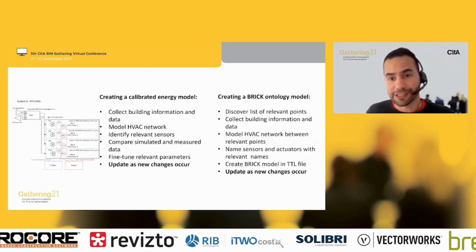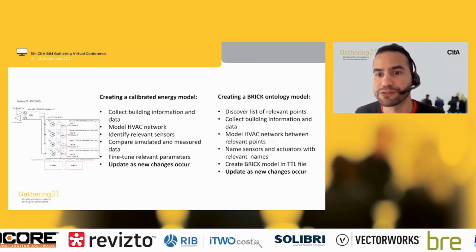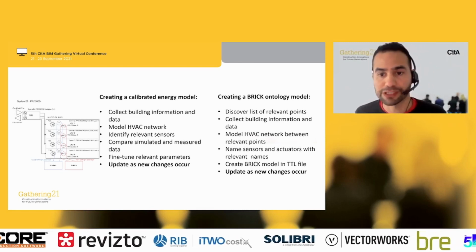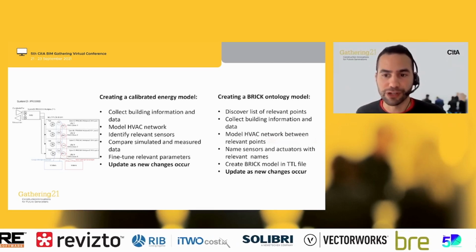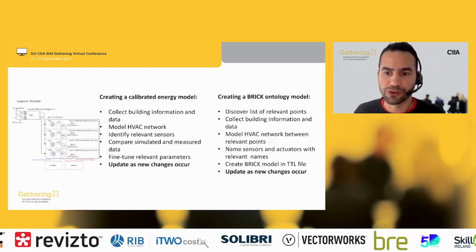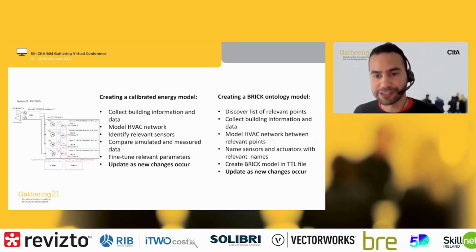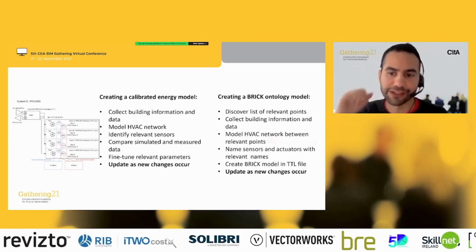On the other side, big companies will have another specialized team for creating the Brick ontology model, for example. What they will do is discover the list of relevant points, collect the information of the building, model the HVAC network and its relationships, name the sensors, create the Brick model in a Turtle file, and then update as changes occur.